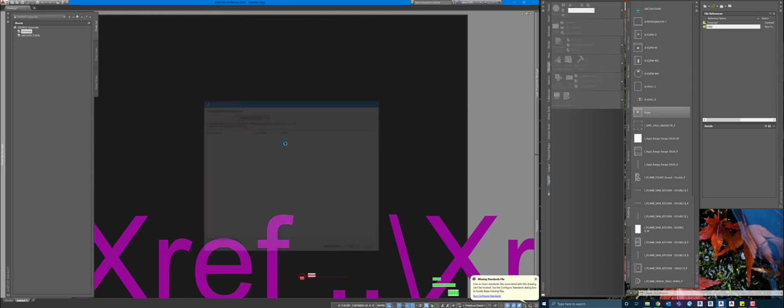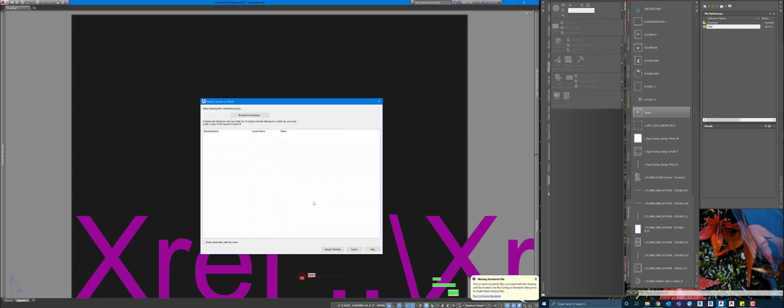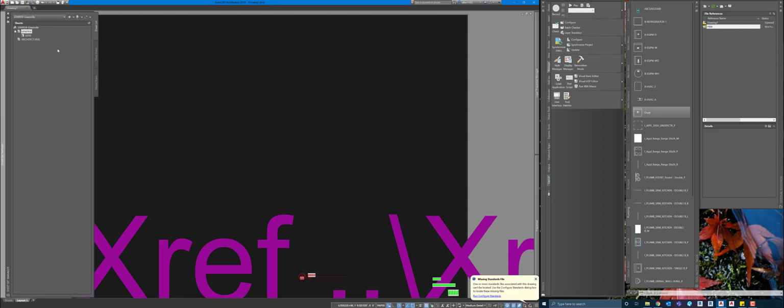You can import layout as sheet. Again, all it's doing is right-clicking. So again, these are from another job, but go ahead and import this guy. Now I have two layouts, but I only want the one layout to be present in the sheet set, so just check that layout. Say OK. I get a warning saying that it may be associated with another sheet set, and at one point that was true because I did copy it from another job where it was associated with another sheet set. But because I've moved the files, it broke the links, so it's not an issue.